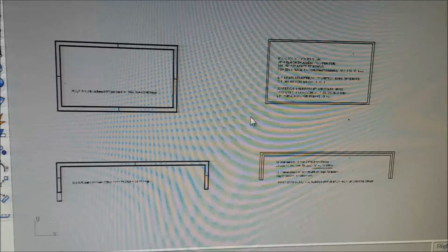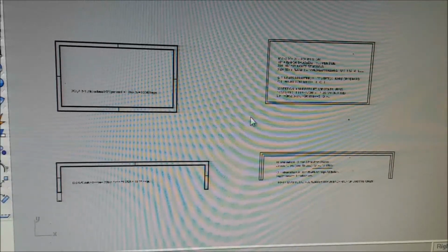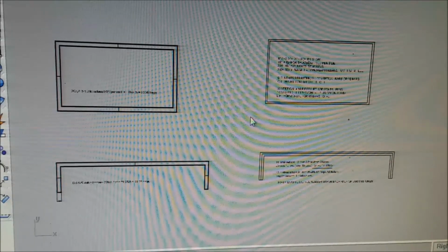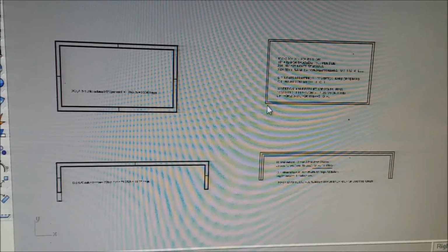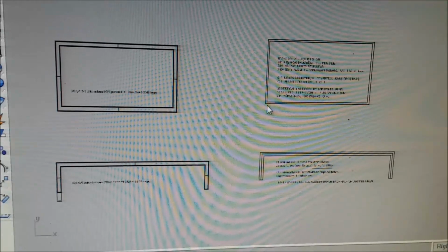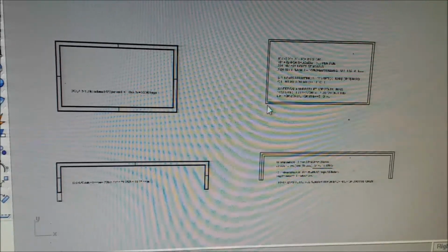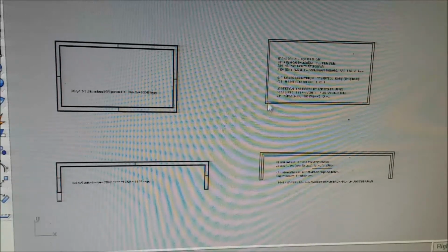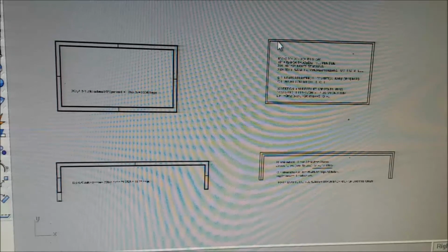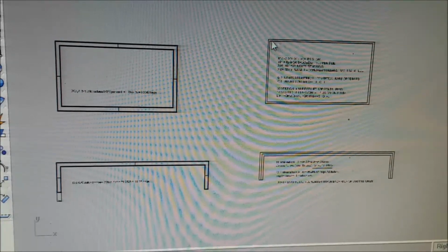If you have tie beams and under the ground and over the top and all that, you're still going to have tie beams. If you're doing poured concrete, it may only be the same width of the wall, because the whole thing is a column or the whole thing is a beam. You don't have any stress concentrations all carried back to corner posts, because the whole thing is poured concrete, just like the post would have been.